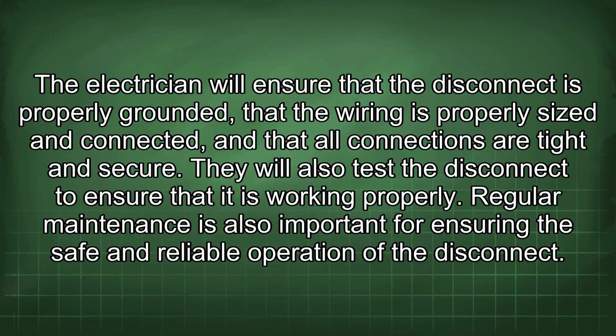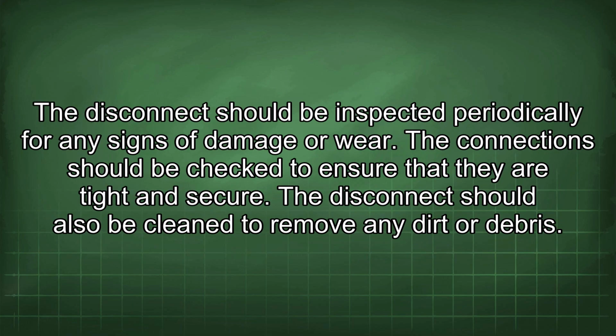Regular maintenance is also important for ensuring the safe and reliable operation of the disconnect. The disconnect should be inspected periodically for any signs of damage or wear. The connections should be checked to ensure that they are tight and secure. The disconnect should also be cleaned to remove any dirt or debris.